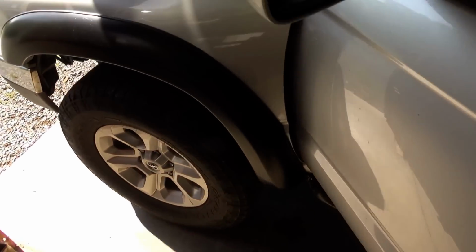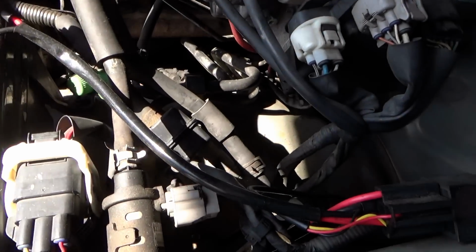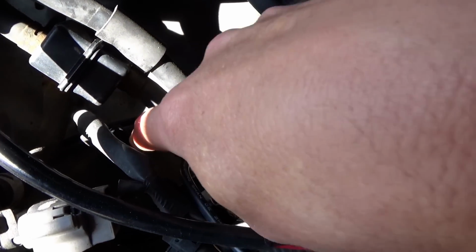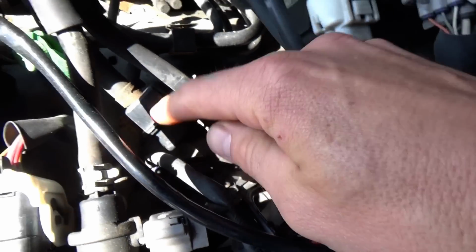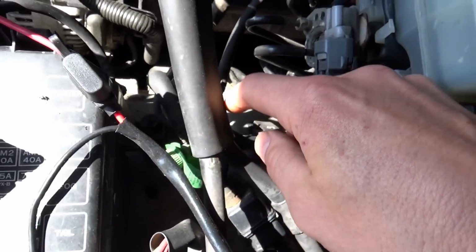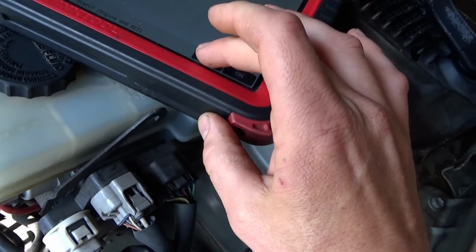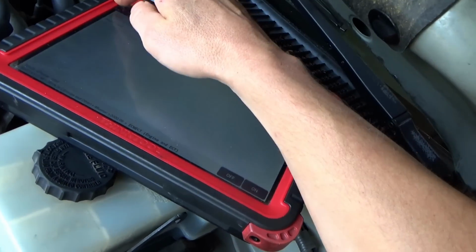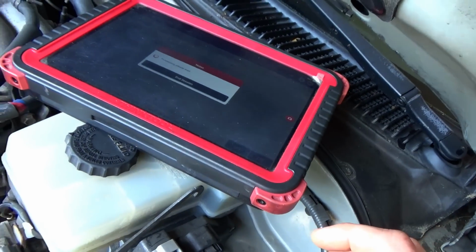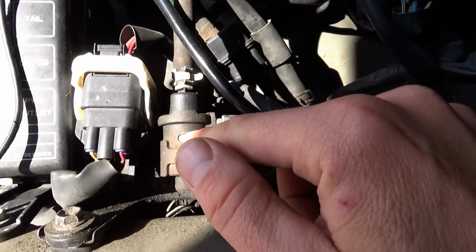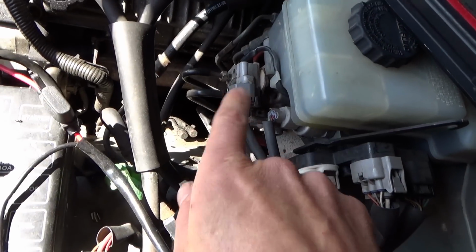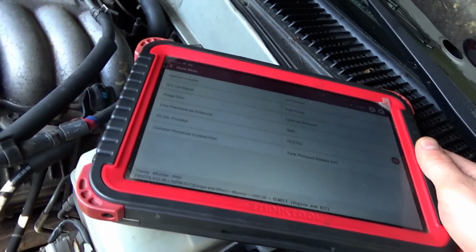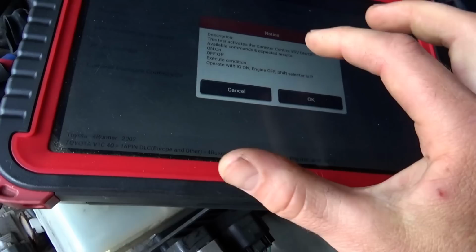And you can hear it's hammering away under the hood. So the purge VSV is right here. This guy right here, see the green cap, purge coming in, and then that goes to the intake manifold. So we'll click off. Let's go to the next one. That would be this canister vent VSV, which draws fresh air from the air cleaner and then sends it back to the canister. So canister pressure control VSV.